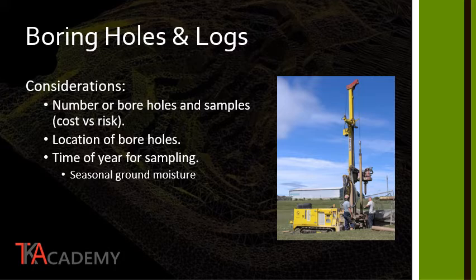Diverse sites with a lot of variation pose greater risk and therefore warrant a greater number of boreholes and soil samples to be conducted. Likewise, projects with large footprints can have a lot of subsoil variation, therefore a greater number of boreholes and soil samples should be conducted.